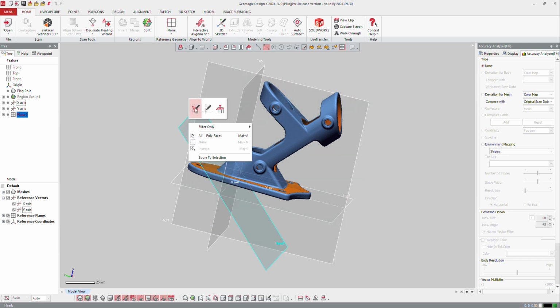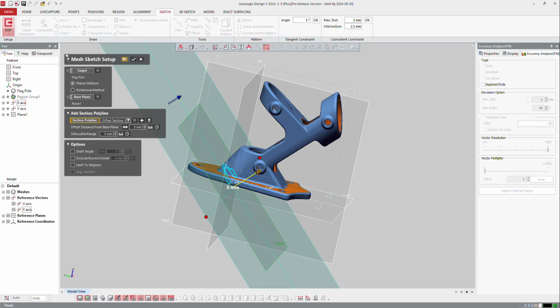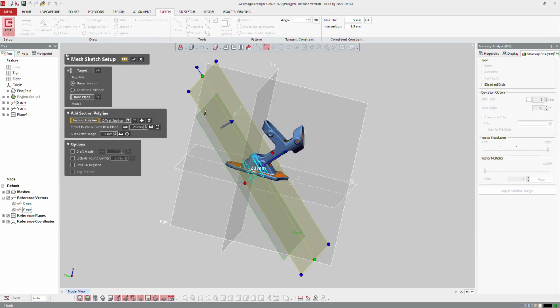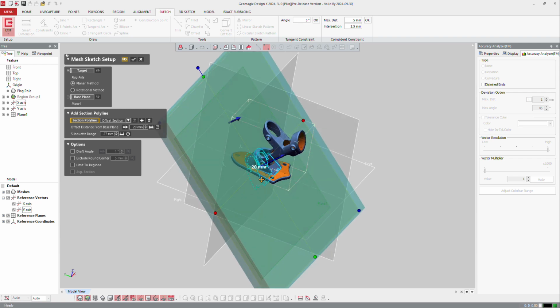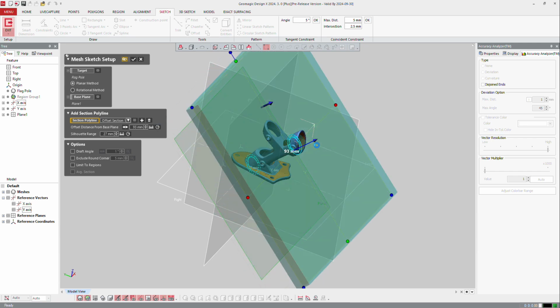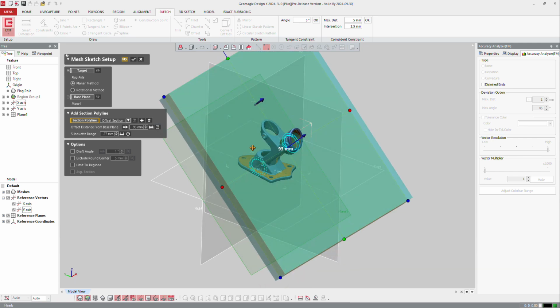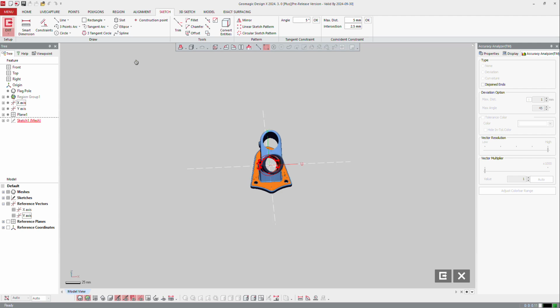I will make a sketch on the part and move it up just to get the global shape of that part. If you want, you can ask for silhouette, but I don't want to get that outside, so I will move it up. Okay, to get the cylinder here. And okay. From that point of view, I will create, based on that center, a center rectangle.